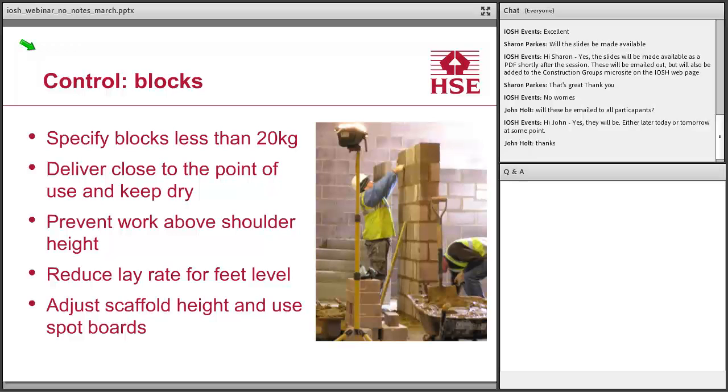Delivering the blocks as close to the point of use as possible by mechanical means, and keeping them dry. Looking at trying to get the work between shoulder and knee height. Again, it reduces the way the brickie uses his body and prevents injuries.